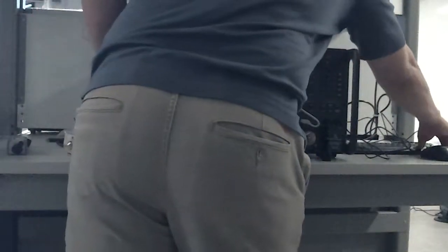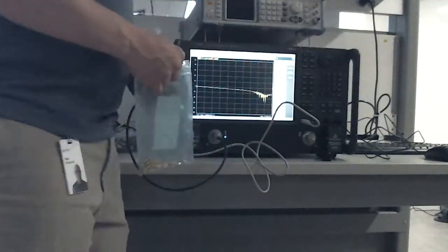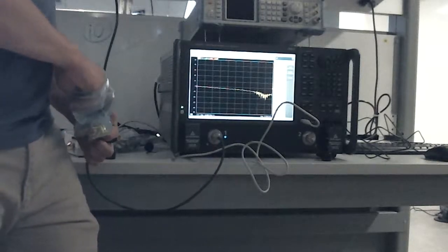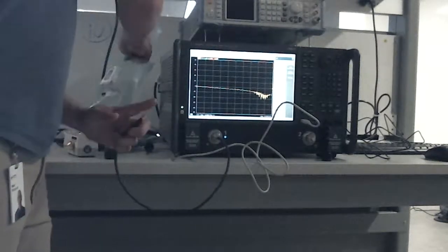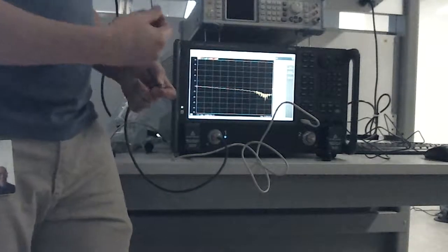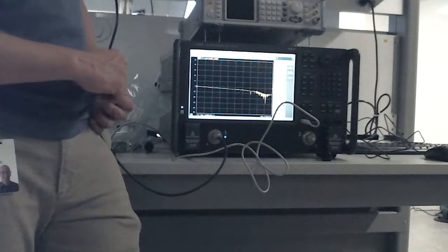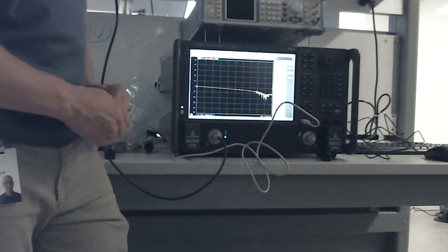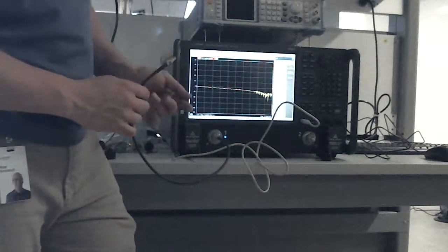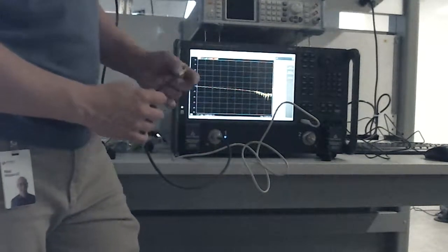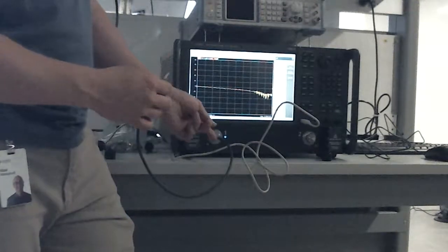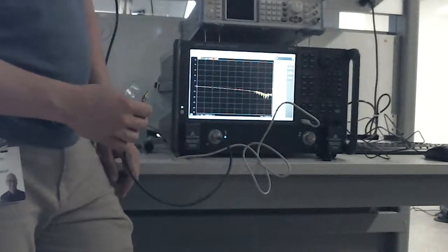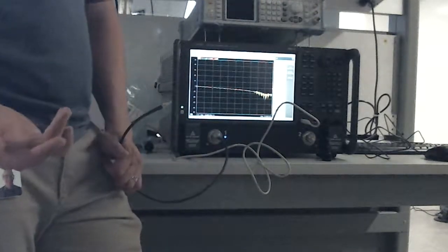So one of the ways that I can see how good everything is, is to say, okay, what happens if I just use a female adapter in here? Because this is not really an open, right? It's an open plus some fringing capacitance that is variable. But if I use a bullet, I can take a look at a little bit more interesting things. And what this might tell me is that this response is actually coming from the cable jacket itself. So this tells you the quality of the cable that you're using.